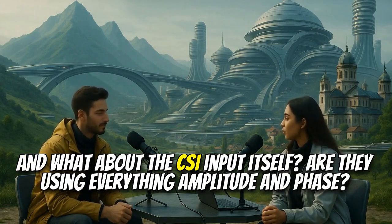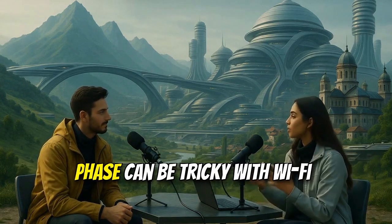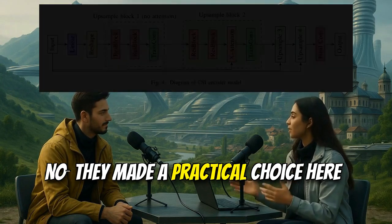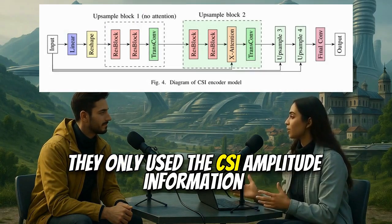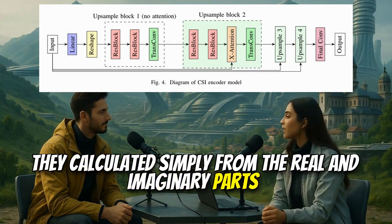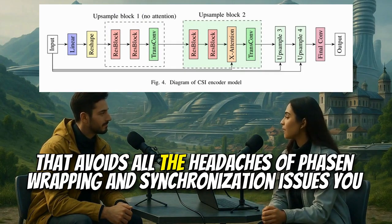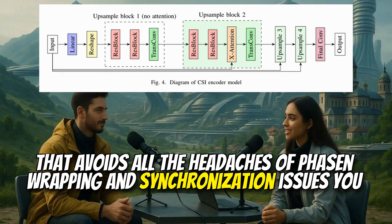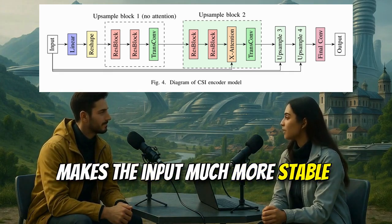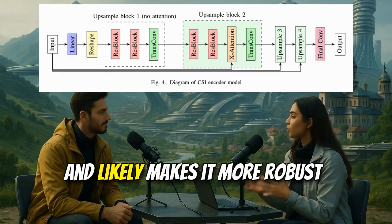And what about the CSI input itself? Are they using everything, amplitude and phase? Phase can be tricky with Wi-Fi. Good point. No, they made a practical choice here. They only used the CSI amplitude information. They calculated it simply from the real and imaginary parts. Smart. That avoids all the headaches of phase unwrapping and synchronization issues you get in real-world Wi-Fi setups. Makes the input much more stable. Definitely simplifies things and likely makes it more robust.